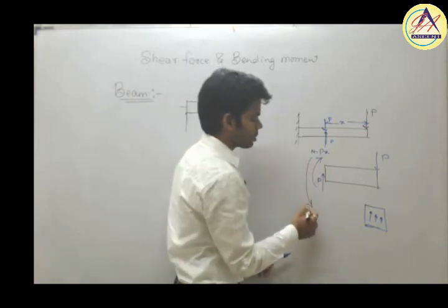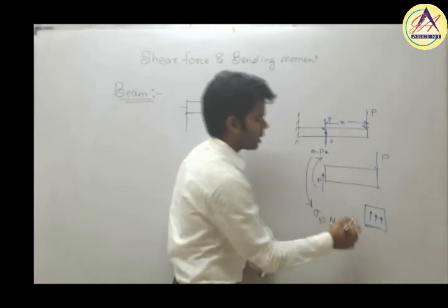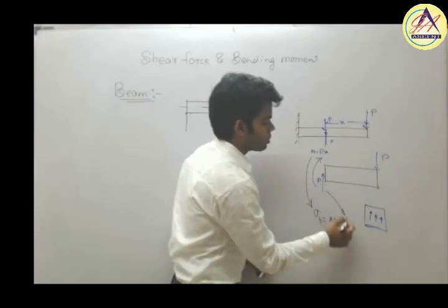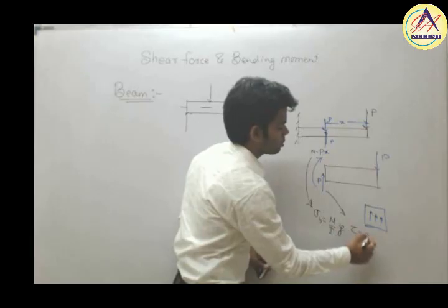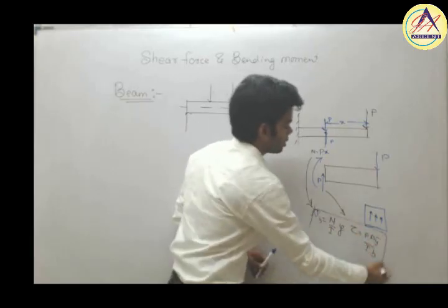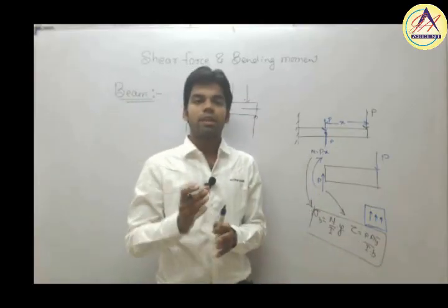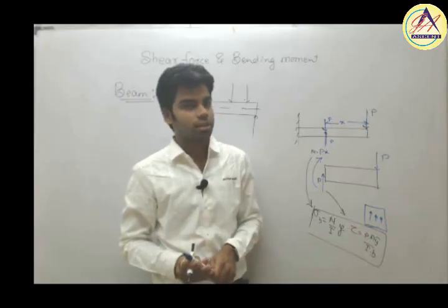Because of this bending moment, bending stress is produced, whose magnitude is equal to M by I into Y, and because of this shear force, shear stress is produced, whose magnitude is equal to P A Y bar upon I into B. This we are going to see in the further units. Okay, so what should be the first step? To determine the shear force and bending moment in any beam.